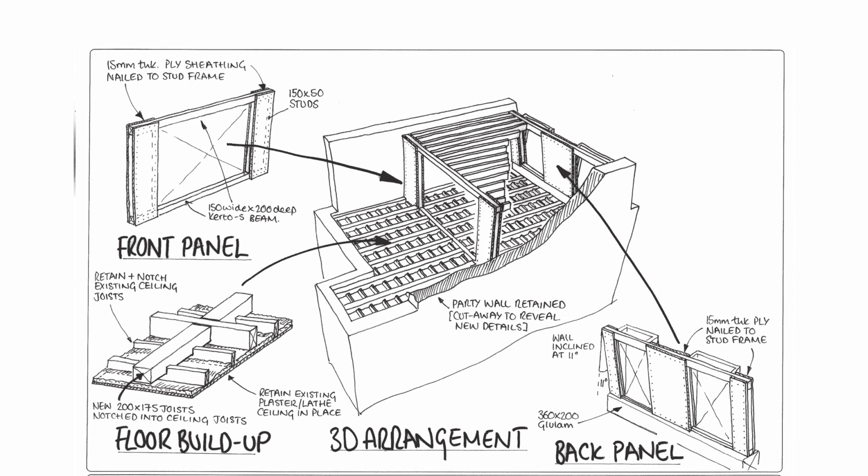This is an example of a good use of perspective drawing, as it gives us an impression of looking down on a space that has had a wall cut away to show details. The engineer has itemized the components in the small isometric sketches surrounding the main drawing. The whole sheet is evocative of the construction process and represents the engineer thinking through and communicating assembly details.